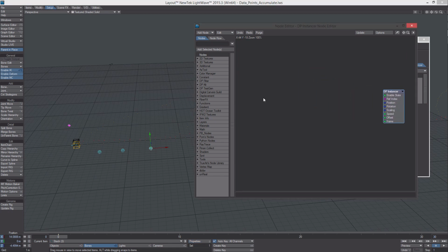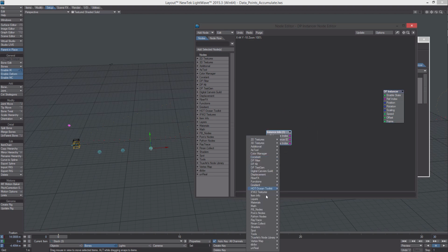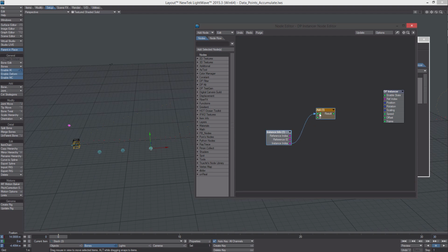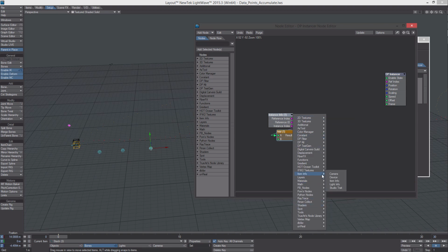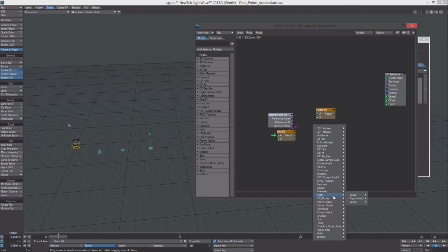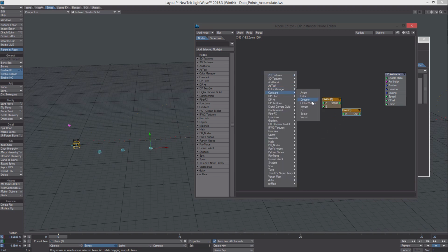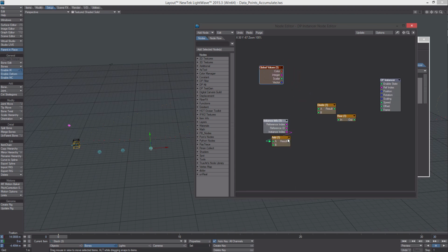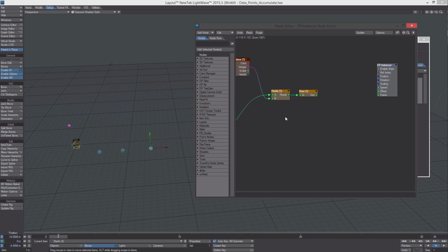And what we want to do is we want to use these bones to manipulate our stacks of 20 or whatever we want them to be. So I'm going to get an instance info, and I'm going to subtract 1 because that starts at 1. We want to start at 0. And we're going to get a divide and a floor. And we're going to get our global variables. So we're going to divide the index by 20 and floor that. And that'll give us groups of 20.